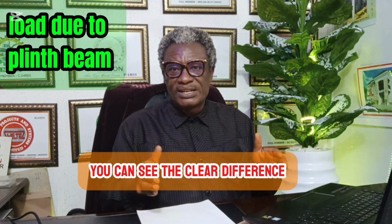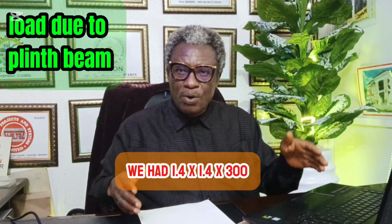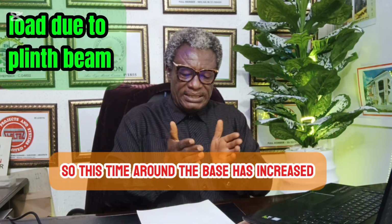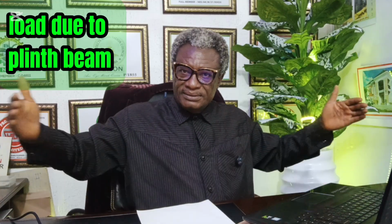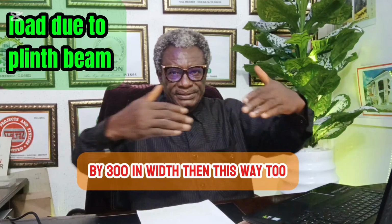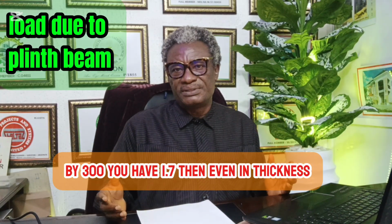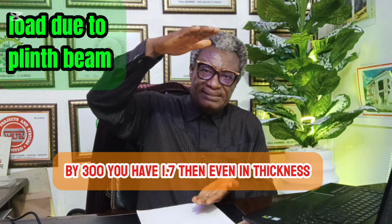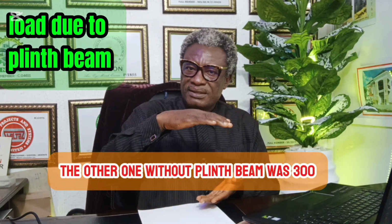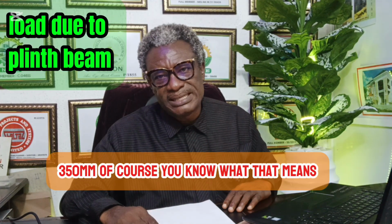You can see the clear difference. When we did the other one, we had 1.4 by 1.4 by 300. So this time around, the base has increased by 300 in width, and this way too, by 300, you have 1.7. Then even in thickness, the other one without plinth beam was 300, whereas in this one, it is 350 millimeters.